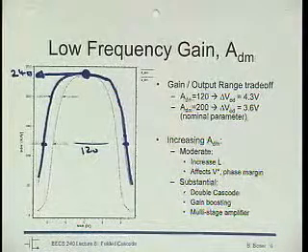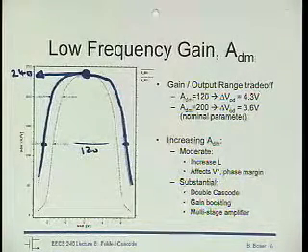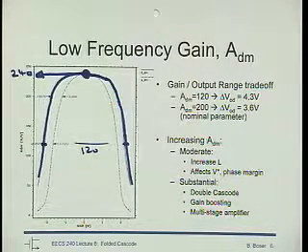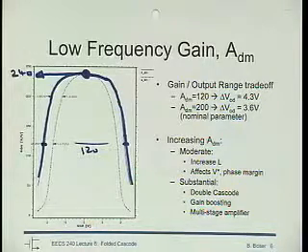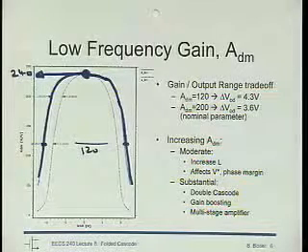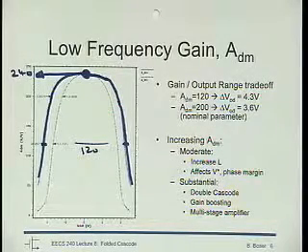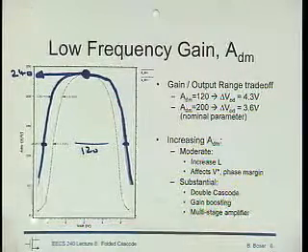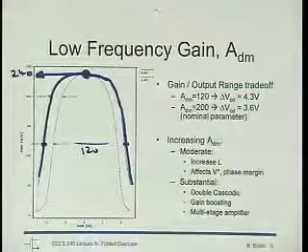We can increase the length of the transistors. That boosts their output impedance a little bit. But of course, then the fT of our transistors gets lower. So if we had a phase margin problem before, now we are going to have a big phase margin problem, right? We could use additional cascodes, or we could use gain boosting.